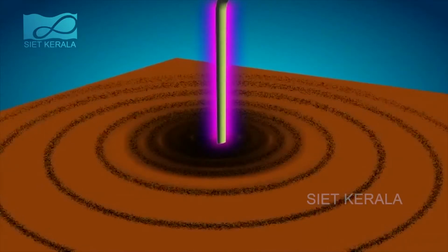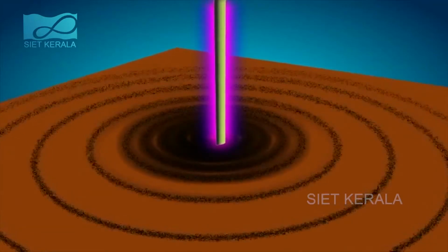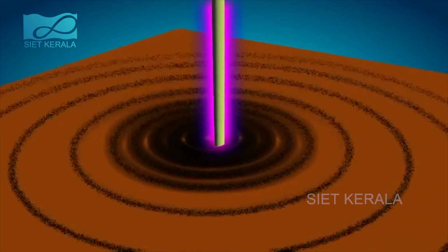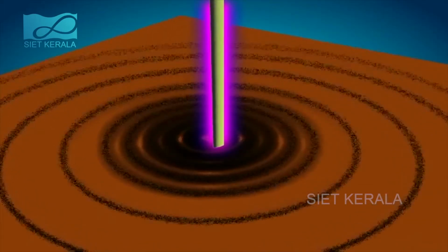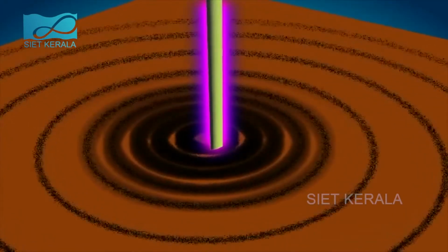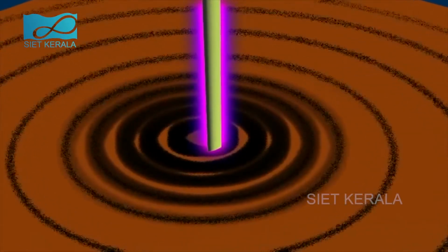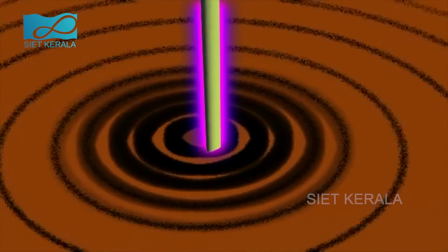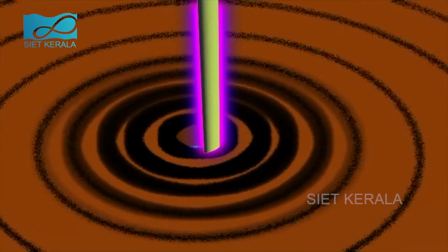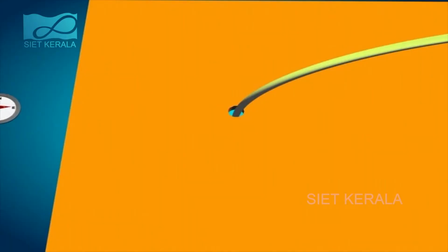Distribution of iron filings is not uniform in all circles. They are crowded near the wire. Iron filings are arranged thickly near the wire, but they become more and more thin away from the wire. Here the conclusion is that the shape of the magnetic flux lines is circular around a straight current-carrying wire. The flux density is greater very near the wire, but as the distance from the wire increases, the flux density is found to be decreased.